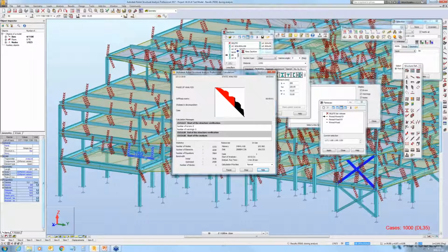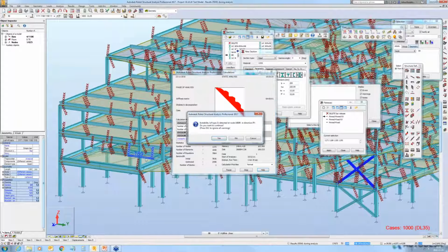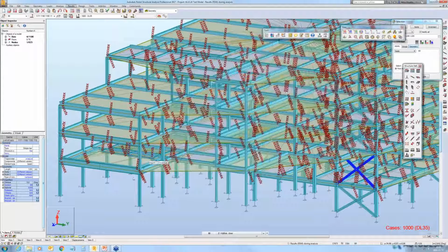So after calculations, what I'm going to look at are the horizontal and vertical displacements. First of all, I do not want to see this 90 millimeters for bracing, and I also want to have a smaller value for vertical displacement for the beams. So that was 88 millimeters or a similar value.